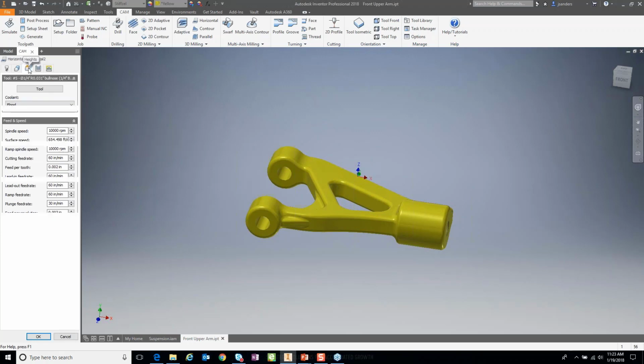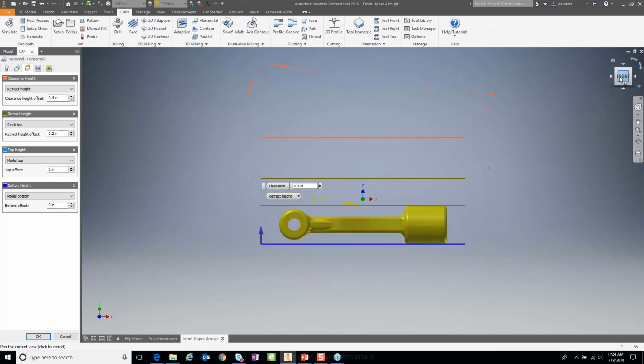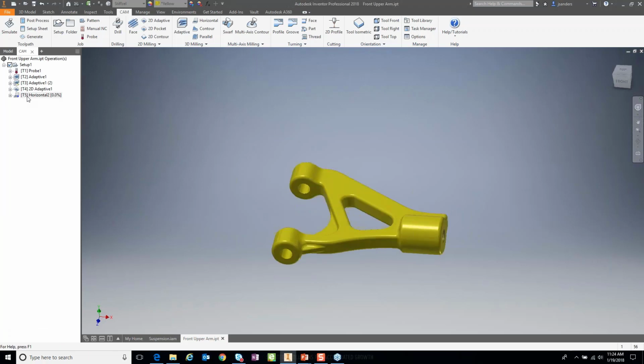In this case, we can refine it by going to the heights. If I look in from, say, a front plane, we look at the different heights that we have available to work with here. Let's go to this height here, and notice that I can drag this up or down. Let's drag down till we're just below the crowns, just by eye, and then say that looks good. After pressing OK, we look at the resulting path. Now we have path just across that top face.